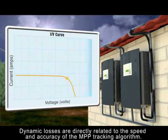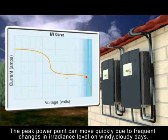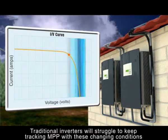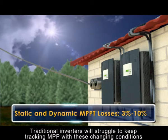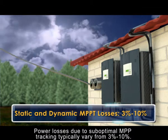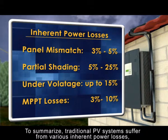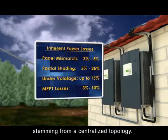Dynamic losses are directly related to the speed and accuracy of the MPP tracking algorithm. The peak power point can move quickly due to frequent changes in irradiance level on windy, cloudy days. Traditional inverters will struggle to keep tracking MPP with these changing conditions. Power losses due to suboptimal MPP tracking typically vary from between 3 and 10%. To summarize, traditional PV systems suffer from various inherent power losses, stemming from a centralized topology.